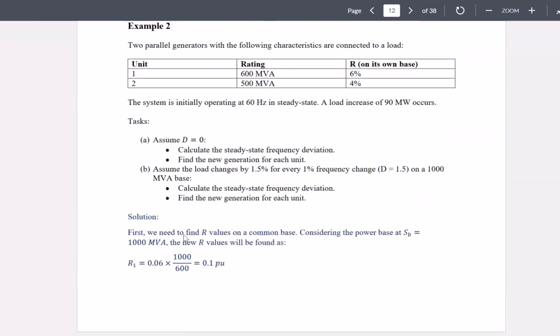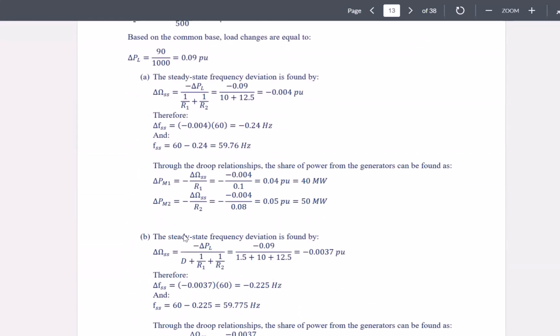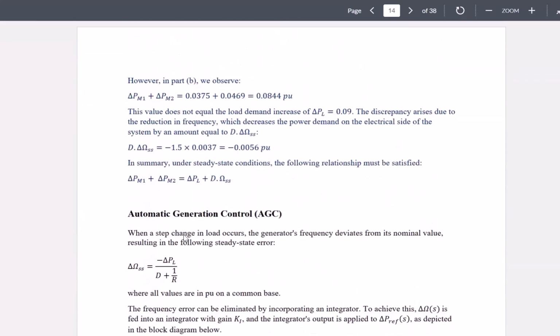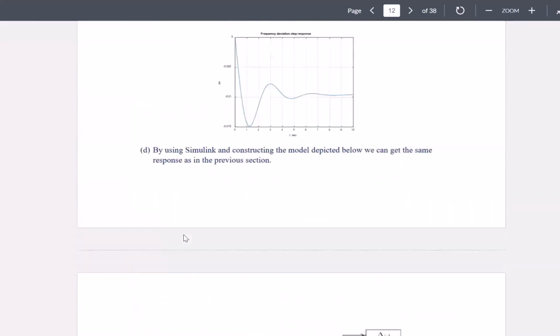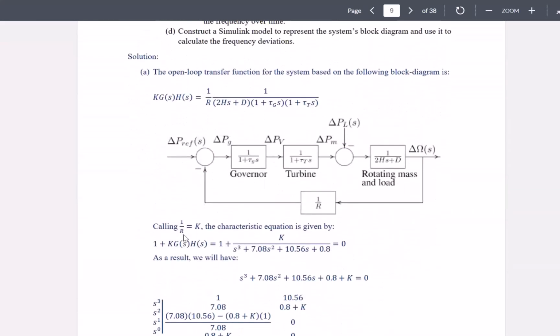So far, we talked about one single generator or multiple generators working together for the same pool of power. And we saw that we were not able to correct the frequency back to 60 hertz in these circumstances. This was the closed loop that we had. We made changes to the load. We saw some errors in frequency, and there was nothing we could do about it.